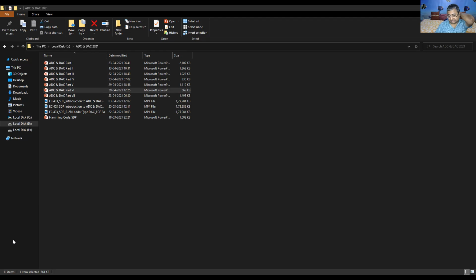So the bits should be B0 to Bn-1 as the output. In other words, the output of the T flip-flop will not change until the MSB bit Bn-1 changes from 1 to 0.